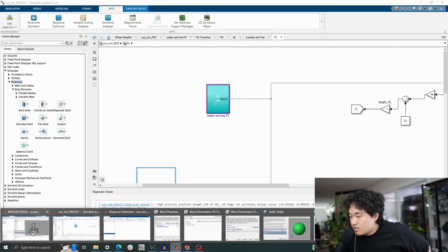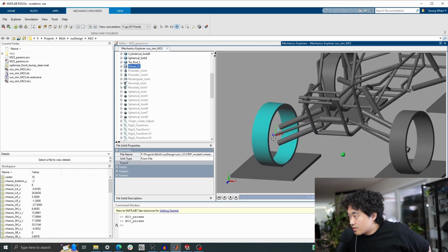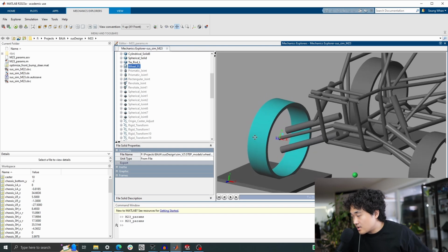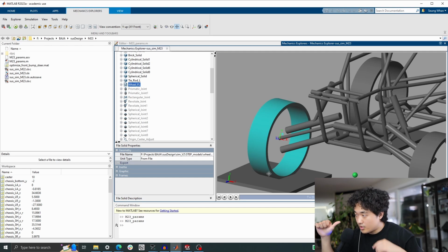Let's go to the wheel origin, right? So that's the wheel origin. It's visualized right there. So you can see the z-axis points out and slightly up. It doesn't point perfectly straight out because of the caster angle, but it doesn't really matter in this case. I already accounted for that, and honestly, I don't think you even need to account for that. But you could, as we can see, if you follow the right hand rule, with your thumb pointing at the axis of rotation, then your camber corresponds to rotation about the z-axis, and your toe angles correspond to rotations about the y-axis.